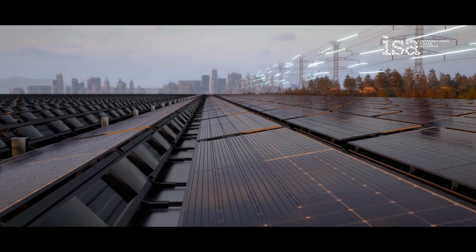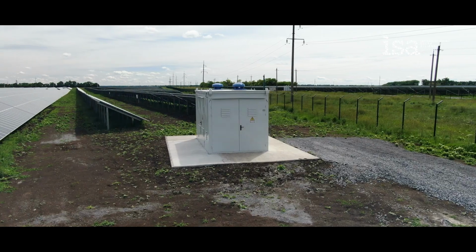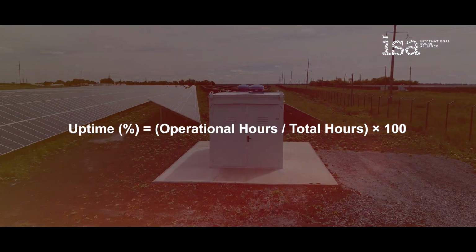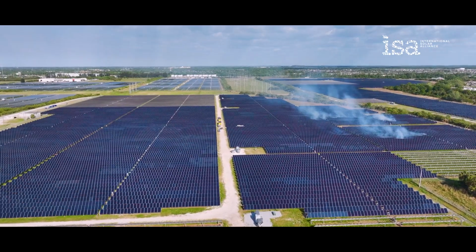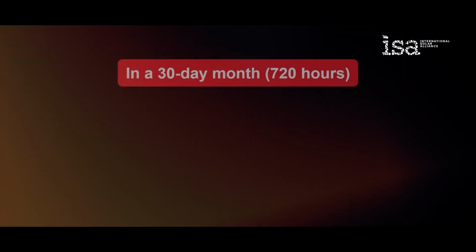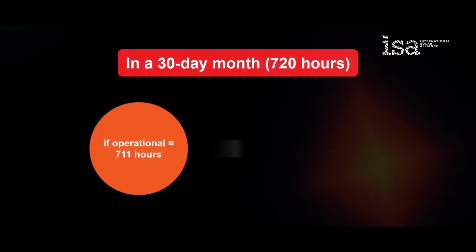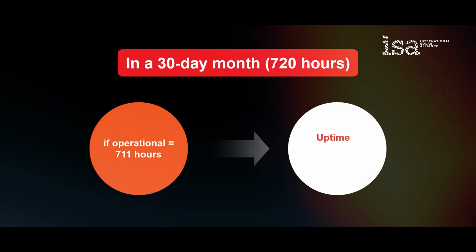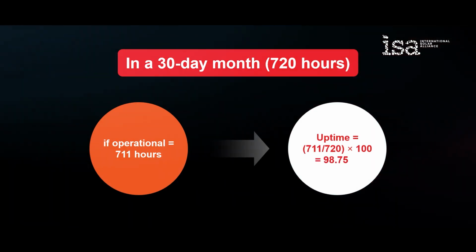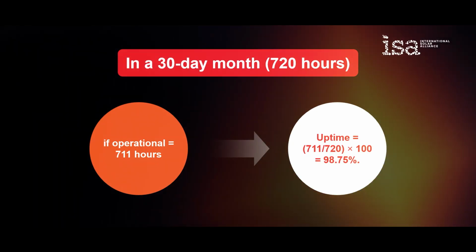Uptime is the percentage of time a plant is operational. High uptime equals higher energy production. Uptime, % equals operational hours divided by total hours times 100. Downtime includes planned maintenance and unplanned outages. Track both planned and unplanned separately for root cause analysis. Example: in a 30-day month, that's 720 total hours. If operations run for 711 hours, then uptime equals 711 divided by 720 times 100 equals 98.75%.